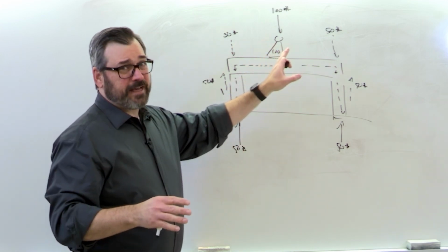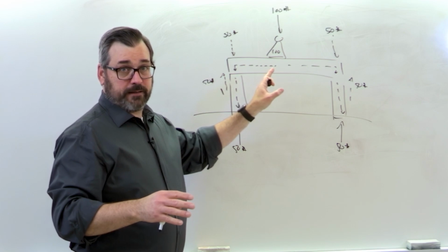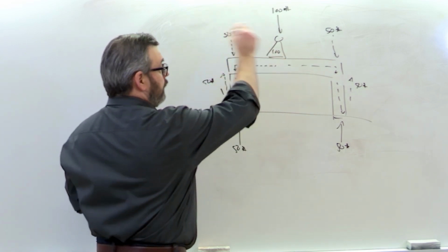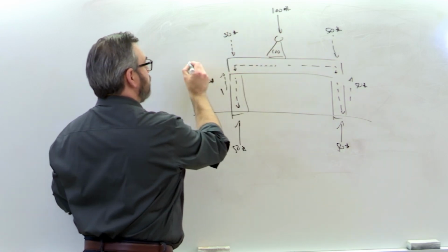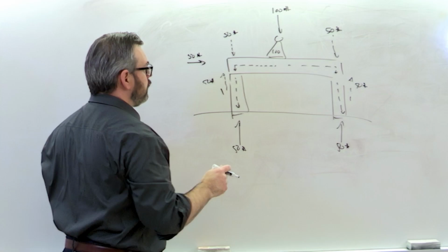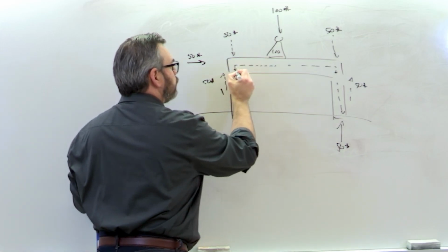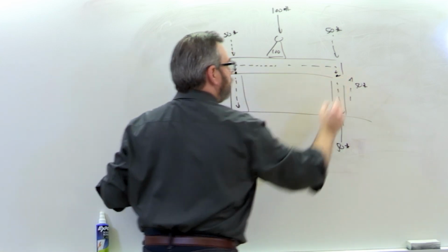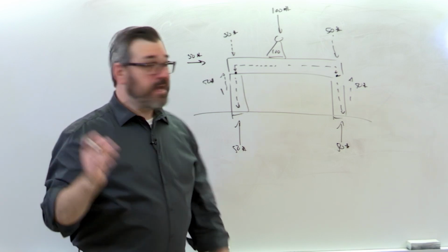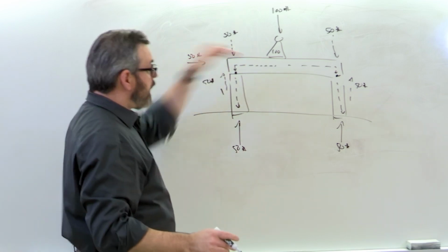This didn't really take into account fixity of joints. We were assuming everything up and down. So if we imagine as well that there's a dancer up here now and somehow they are imparting, say, 50 pounds of force that way from a move that they do in that direction, we now have to think about how does this joint, which we're assuming is fully pinned, it's just going to rotate, how does that resist that movement?